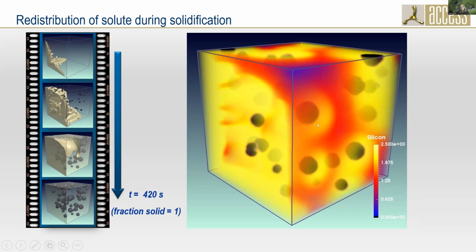You can also see that silicon is segregating negatively here, so in the end we get the smallest amount. And you also see that the highest amount of silicon is in direct vicinity of the graphite, and also where the primary austenite dendrite had been.